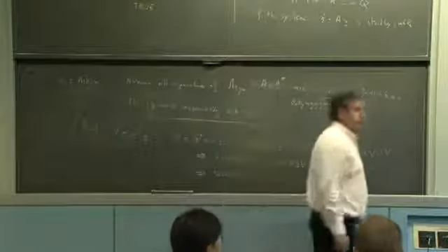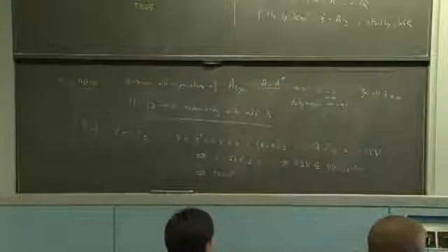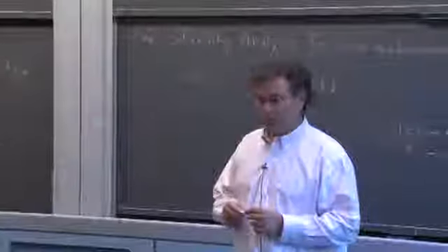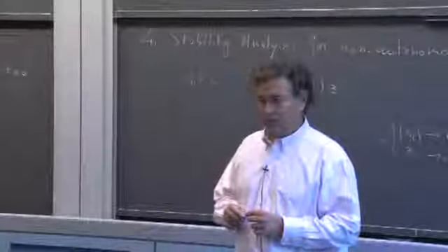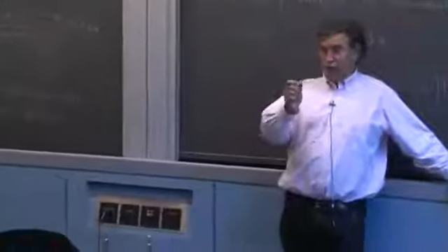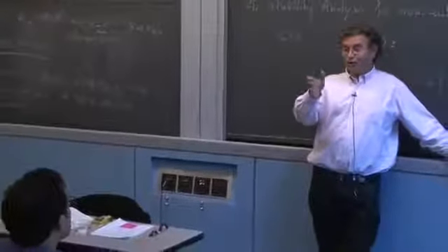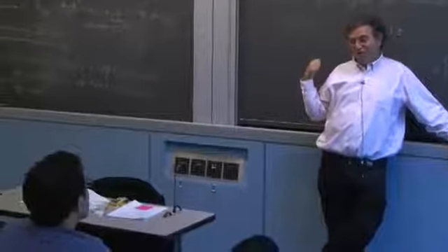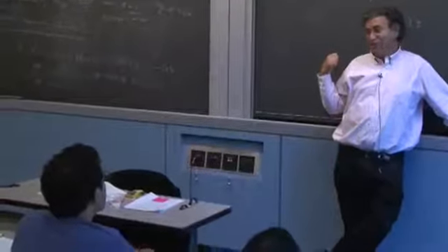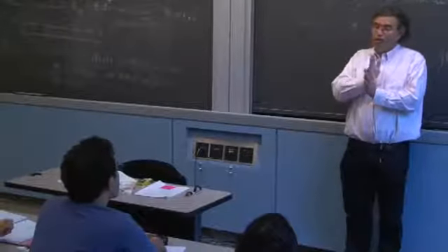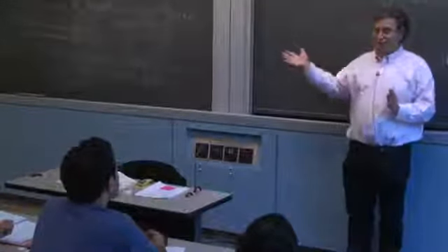Yes? Can we then say that for a linear time invariant system, if the system is stable, then the eigenvalues of the symmetric part are definitely negative? No. Actually, it's a good point. And that's what we just saw when we saw Lyapunov theorems for linear time invariant systems. We said it's not true that if you pick P equal identity, then Q will be negative definite.